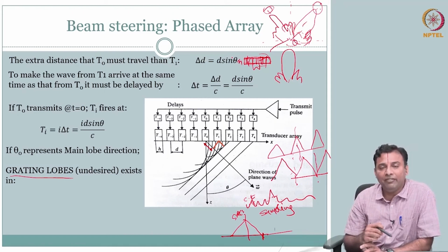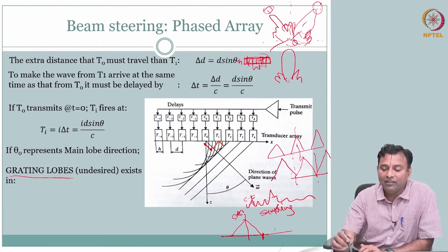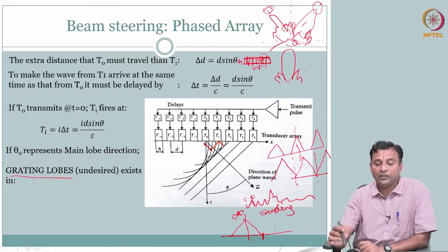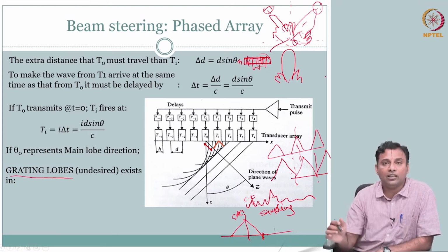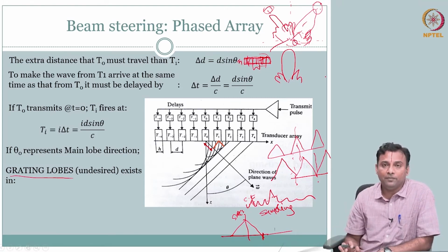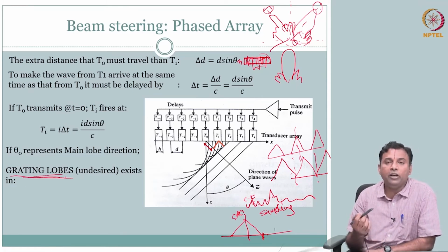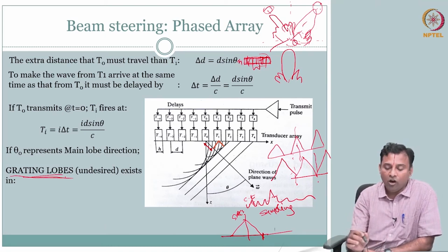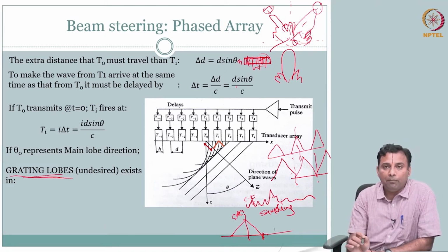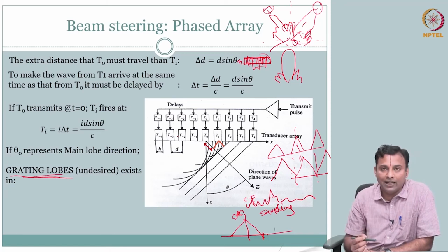If I sample very well, that is greater than your Nyquist, I should have these not overlap. I should have multiple copies, but the other copies should be small. So in order to avoid this grating lobe, there is going to be a constraint on how well you sample. The sampling parameter here is D, how close the two elements are.